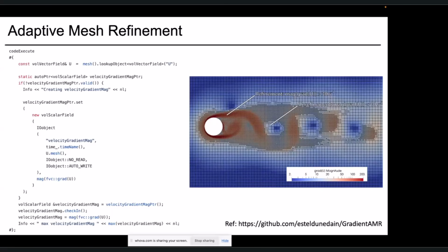Is that we can calculate the velocity gradient also at runtime with a slight modification of the code, and then track that as the tracking criterion for doing the refinement or unrefinement. All right, so this is a very interesting option, which gives you the outlook that it is not only an explicitly mentioned scalar variable, but it can also be implicitly calculated during your solution, and in turn can be tracked for doing the refinement and unrefinement.